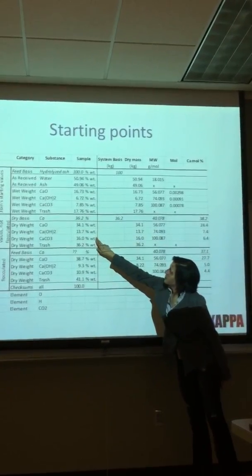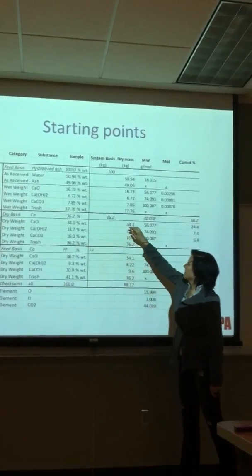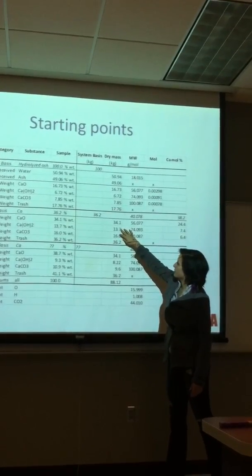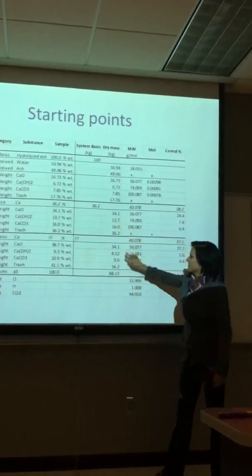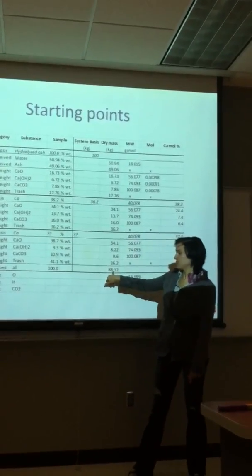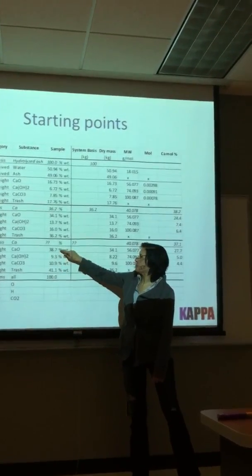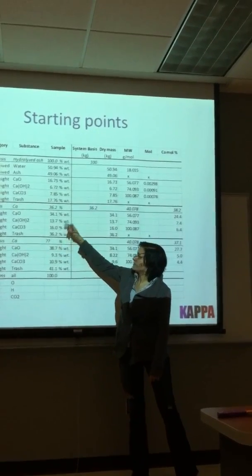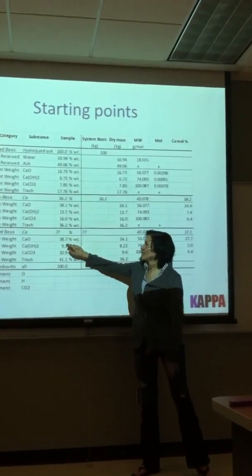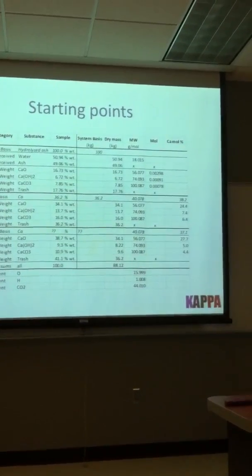I converted the sample percentages, which we were given for dry ash, not flocculated, into dry mass based on molar values, and then removed 40% of that to get these values here. Then I made a total weight and pulled it over into new percentages, which gives us a new dry weight of calcium oxide for me to work with. My process is working with the calcium oxide, his was the calcium hydroxide. 40% of what I'm getting is junk that has to be removed.